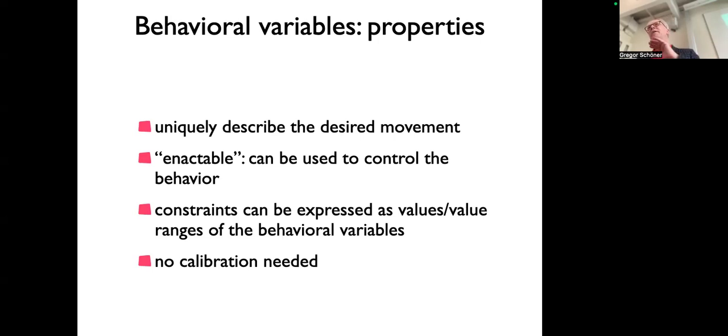So we'll neglect that. We'll say in a good approximation, this can be controlled. That is, if I have a certain heading direction and a certain speed, then I can realize that speed. It turns out that a lot of the approaches we're talking about have some kind of closed loop property. That is, if I consider that heading direction time series to be the plan, and I notice by sensory information that now the target is somewhere different from what I thought, because I didn't actually follow my command, I can update that plan, and that would go in the direction of also stabilizing my behavior. I would, for instance, still go to the target because the target angle changed as a result of me not actually achieving what I wanted to achieve.